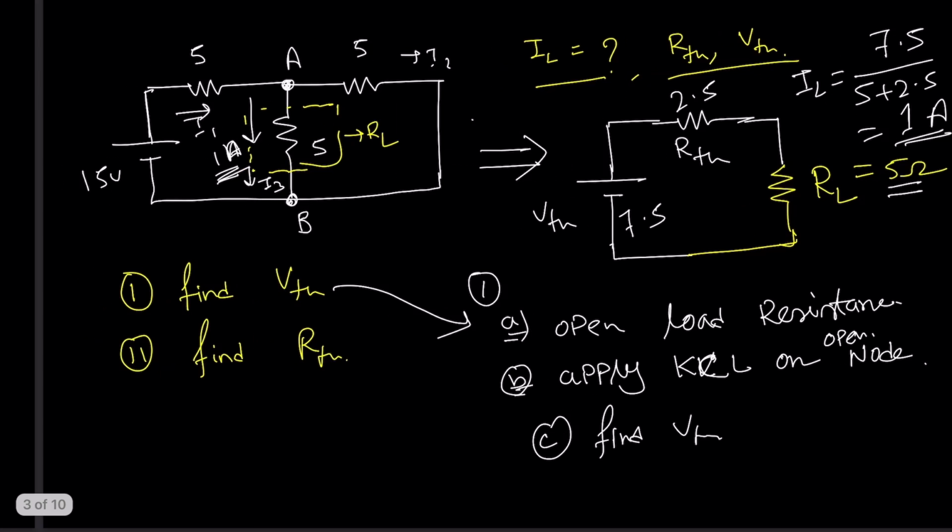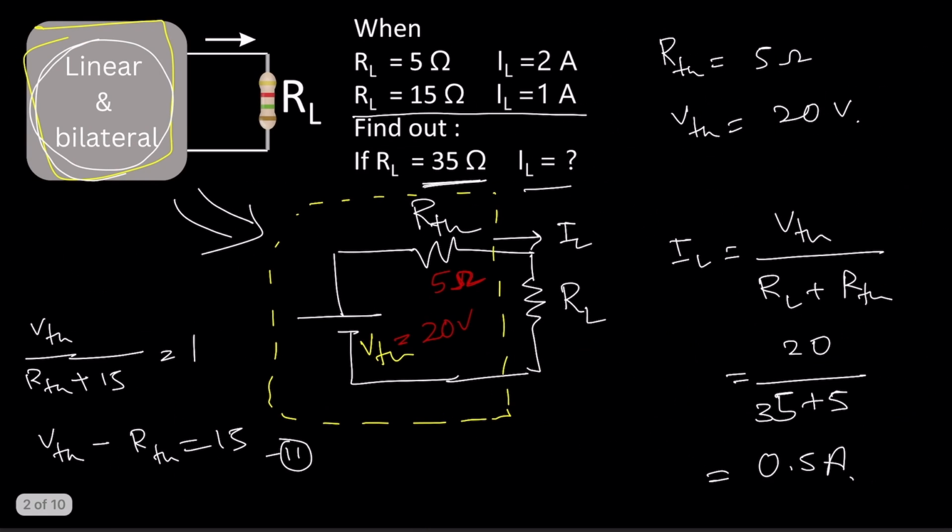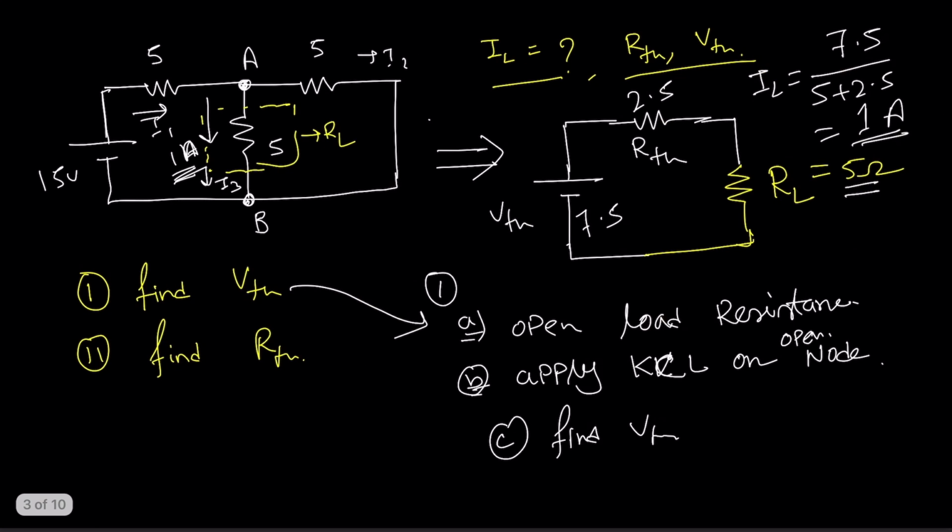Okay. So I already explained the concept of Thevenin's theorem and already showed you two types of problem. This is the basic Thevenin's theorem problem, the fundamental problem, and another is any type of network. In that network, how to apply Thevenin's theorem, okay. I will just summarize the concept. What you need to do? First, you need to calculate VTH and RTH.